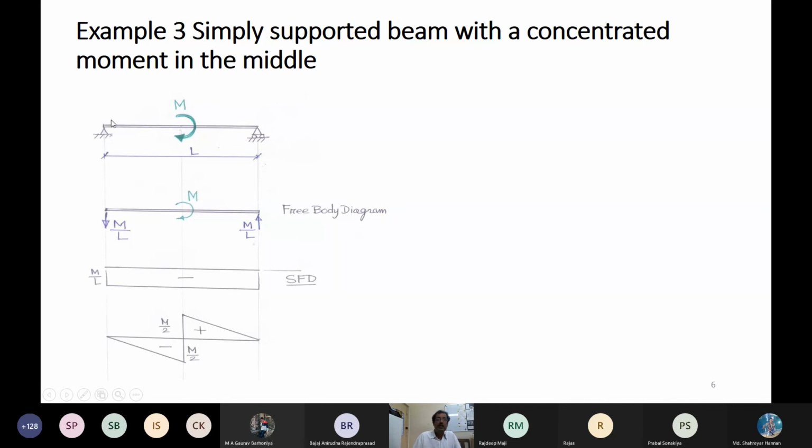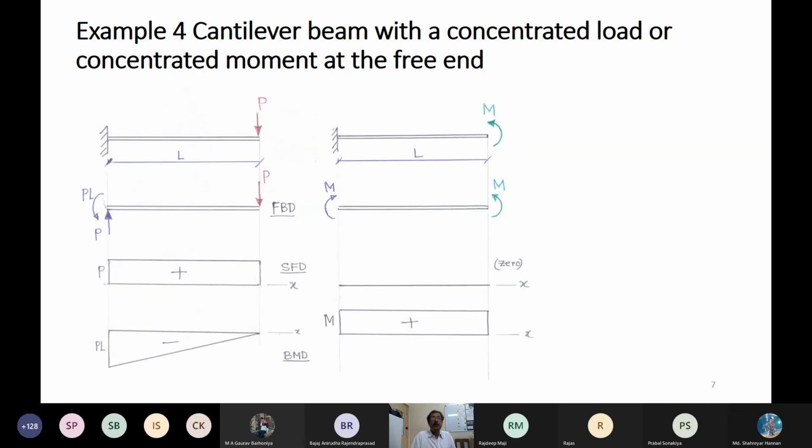Later on, you will find that in the left part of the beam, if it is down, you can say it is a negative shear. Right part up, that is also negative shear, because left up, right down is positive. Later on, you practice this, and seeing that force diagram, you can draw the shear force diagram. But not now. Now you cut the section and do it. Gradually, you will realize that you need not do so. Next problem, cantilever, do it yourself.